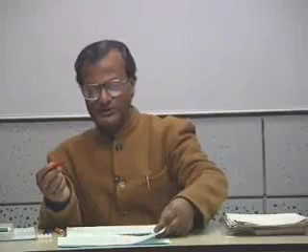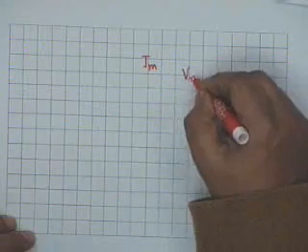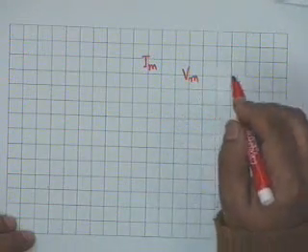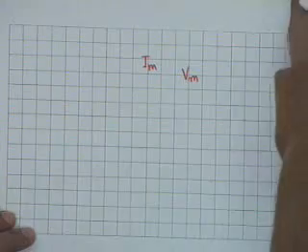So what we can display is the square, not the root, of the quantity. In actual meters, however, the meter is calibrated in terms of the square root of the values. That means it is calibrated to read RMS values, root mean squared values. So DC meters measure the average value, AC meters measure the root mean squared value, and a fourth measure is the peak value I sub m or that of a voltage V sub m, and the peak value is measured by a very simple device.